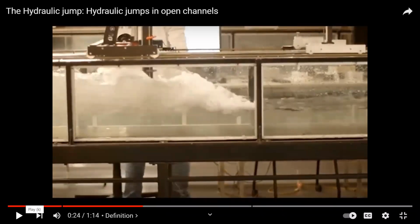Here you can see this region is the supercritical part. Supercritical flow. Then somewhere here, the hydraulic jump happens. The reason is that the flow always tries to minimize its energy. It cannot maintain this supercritical condition.